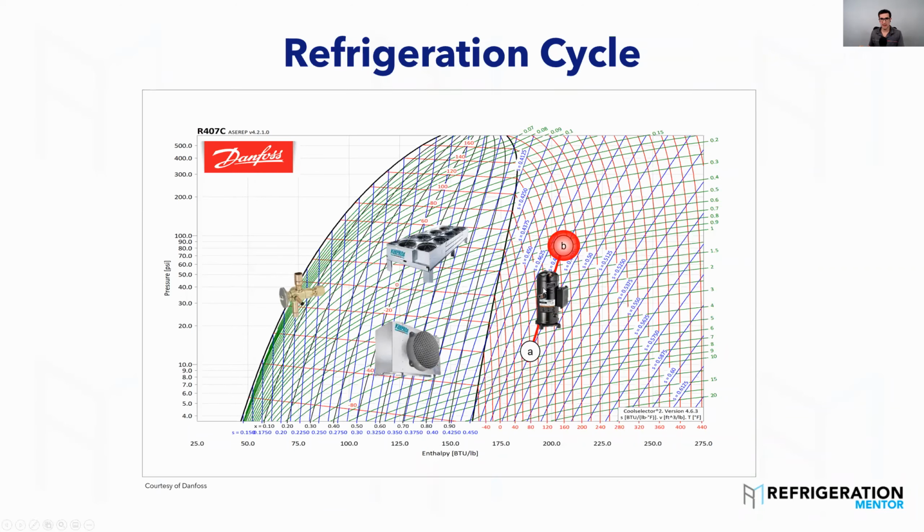Right when it leaves that compressor valve, what starts to happen to the gas? It desuperheats. Right, the hottest point is right when that last squish of gas happens in any compressor. After that, it's all desuperheat. So as it leaves, it's desuperheating.